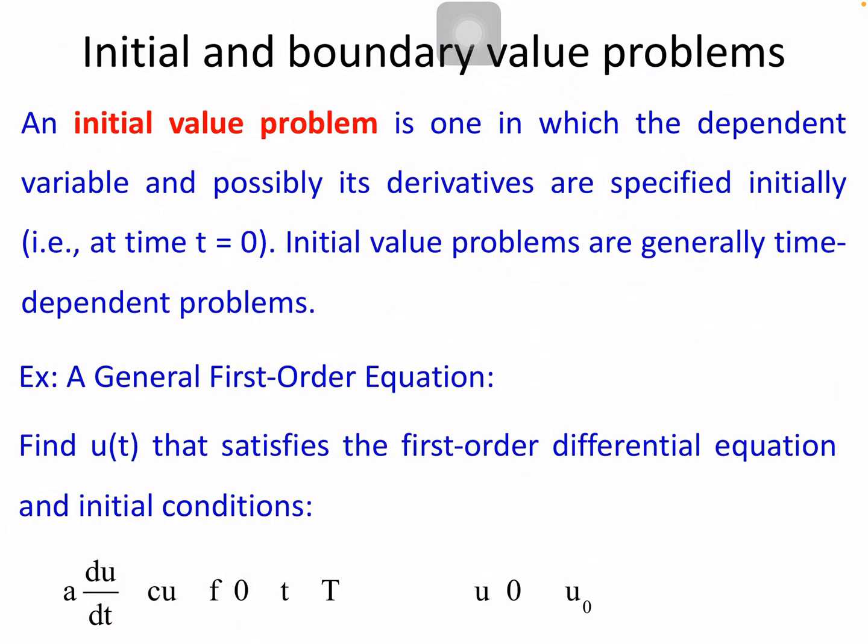Of deformed bodies or theory of vibrations. So there are many equations we see, they are differential equations, right? Even in your strength of materials you saw, right? What, the bending equation, M by EI is equal to d square y by dx square, right? That is the differential equation, the bending equation. Similarly, there are many equations. I think you already encountered such equations in UG itself. So in PG also you are going to witness many such equations.